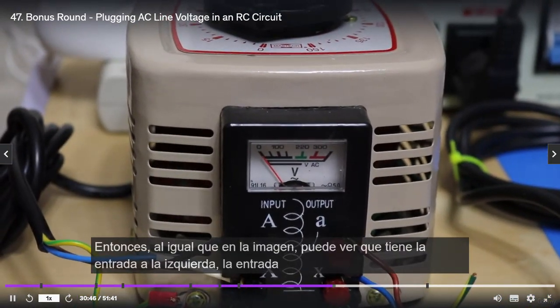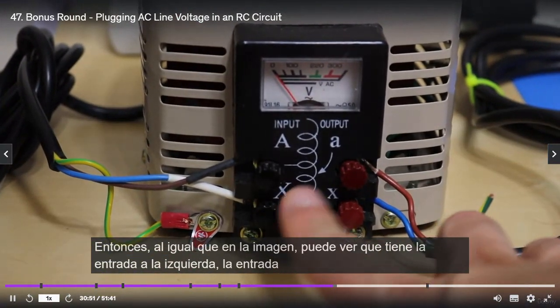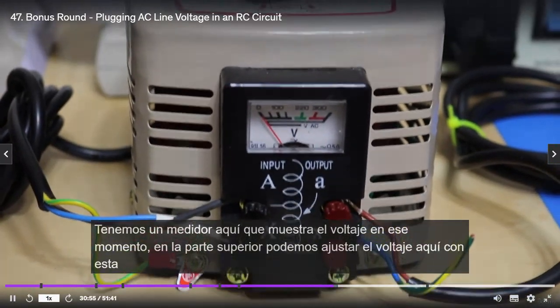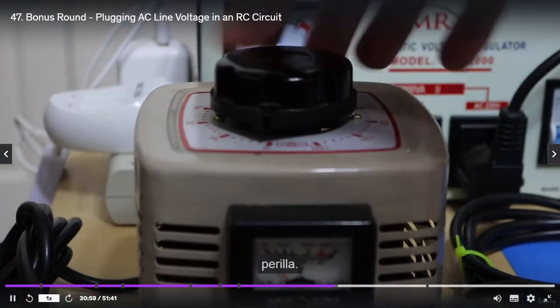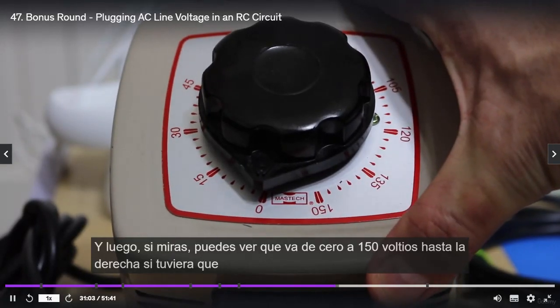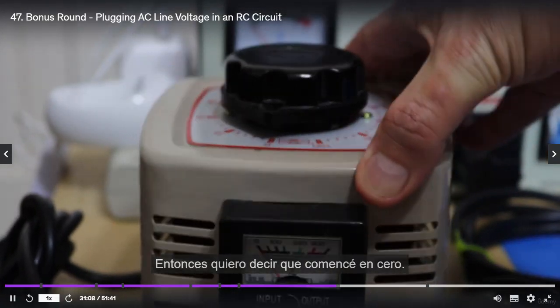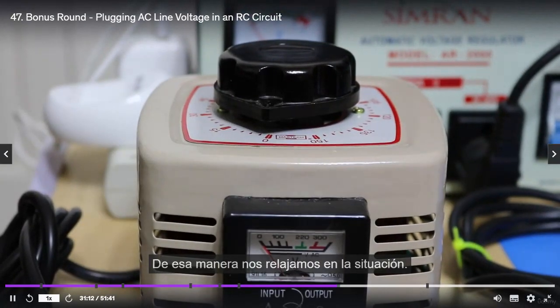So just like it was in the picture, you can see it's got the input there on the left. There's the input. The output is on the right. We've got a gauge here which shows the voltage. Then on top, we can adjust the voltage with this knob. If you look, you can see it goes from 0 to 150 volts all the way to the right if I were to turn it. So I'm going to start it off at 0, and then we can turn it up. That way we ease into the situation.